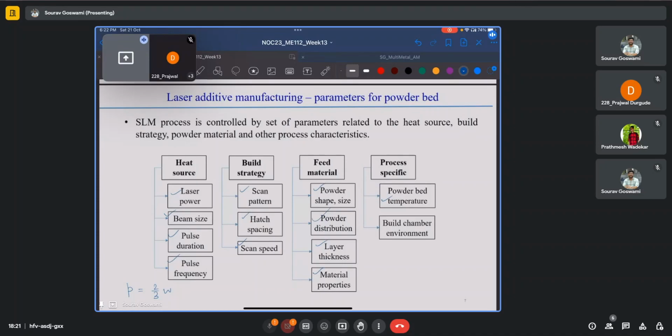And in the second pass, finally, the melting occurs and the particles are fused. Also, the environment, which should be vacuum in case of, say, an electron beam melting type setup, should be purged with inert gases in a powder bed fusion of any reactive metal such as aluminum or titanium, or it can be simply an open atmosphere in the case of binder jetting processes.